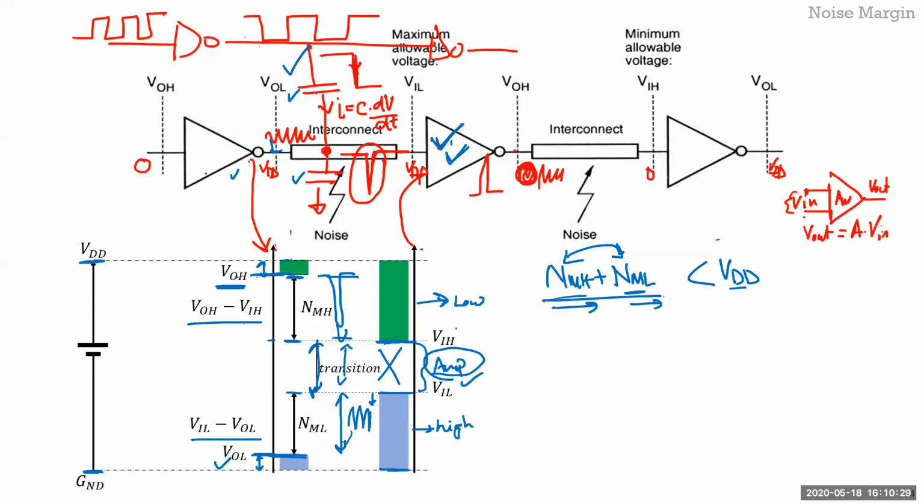In the VTC, we are observing that it is decreasing. There are two points, VIH and VIL. So between that point, the V out is decreasing. In between that transition region, how will we consider the noise margin? Because if we have this VIH and VIL region, in between there will be a transition region, so we can't interpret what the V out will be.